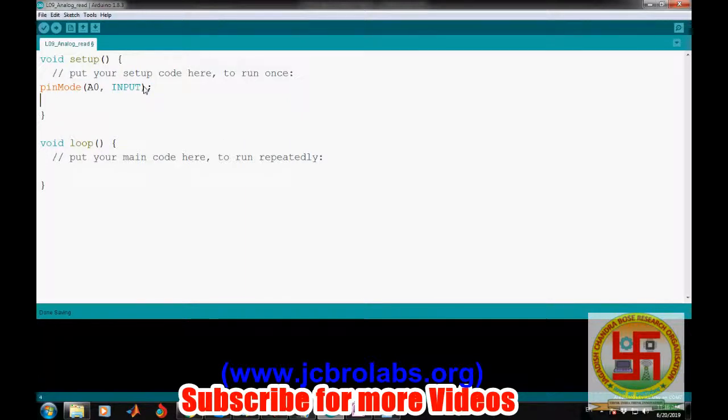And in order to see the result, we will be sending the read data on the terminal as well. Okay, so let's open the terminal as well. Serial.begin at 9600 baud rate, and we will simply be using int a equals analogRead A0, and then we'll be putting it back to the serial monitor.